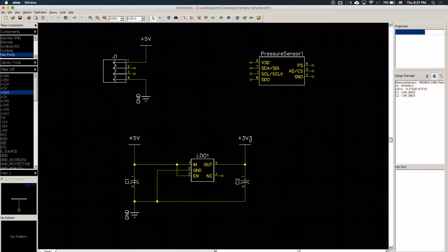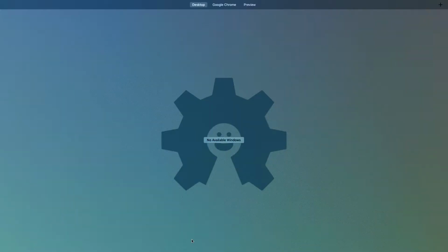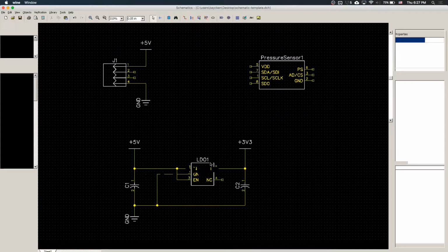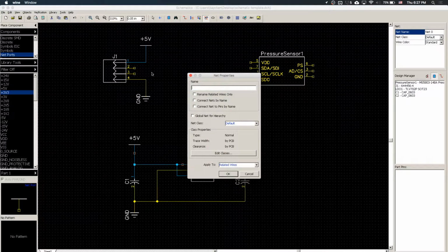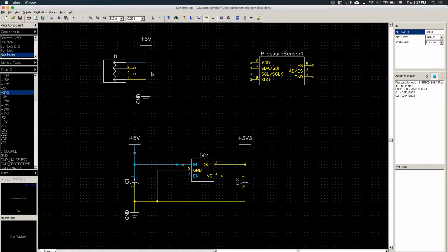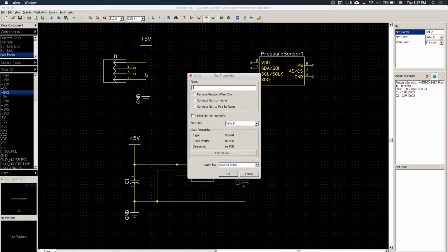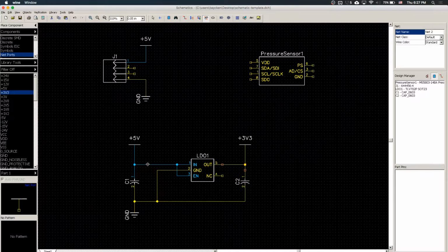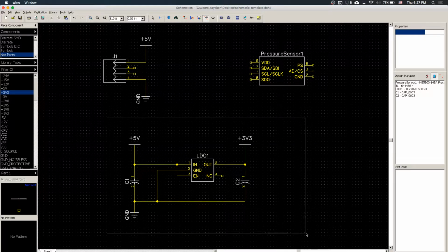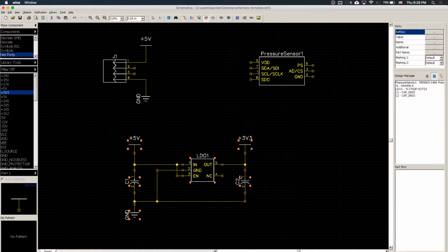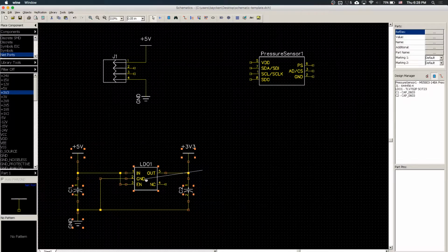Now, although there's a net port to display what the net is, the net will still be unnamed by itself. So what you can do is double click on the net to give it a name. Right now this one will be 5 volt. I'm just going to label this 5V0 and this 3V3. This allows you, when you're doing the layout, to be very clear what this net is, and helps you route stuff easier. As well as I'm going to change the ground net to ground. And that concludes the part that we need to do for the voltage regulator.